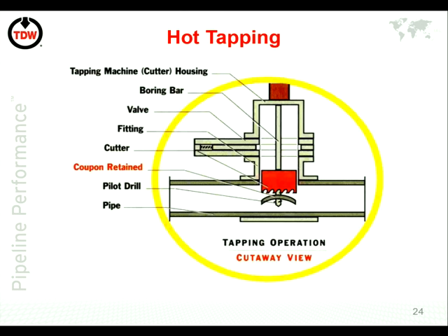Excuse me, please. Sorry. It's okay? How do you cut this coupon and it's so smooth like that? Is the cutter pushing it down? Yes, the cutter is pushing down. So the small ones are pushed down by hand and they're screwed down, the larger ones it's a hydraulic motor and a hydraulic ram which actually takes it down. So it's a big machine. It's a sort of factory produced machine.